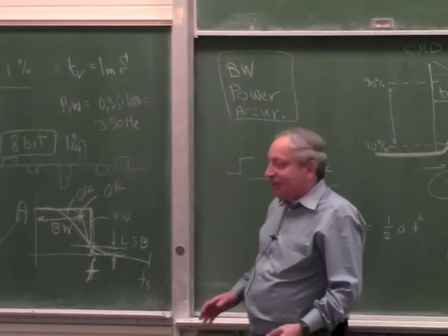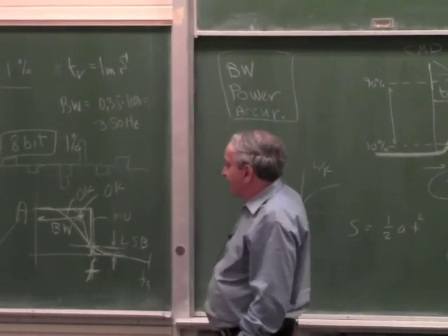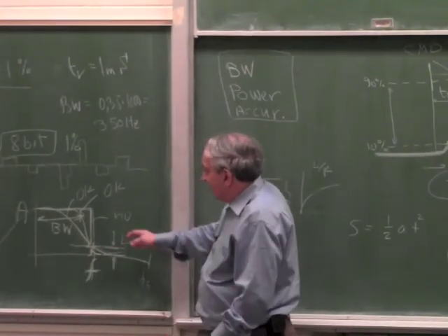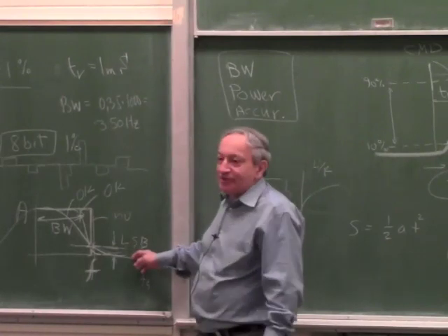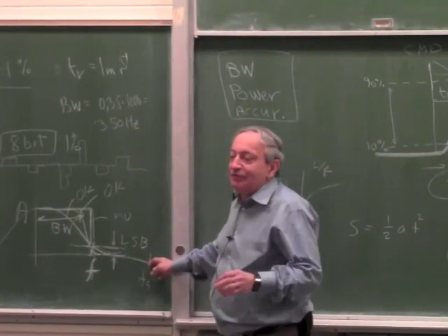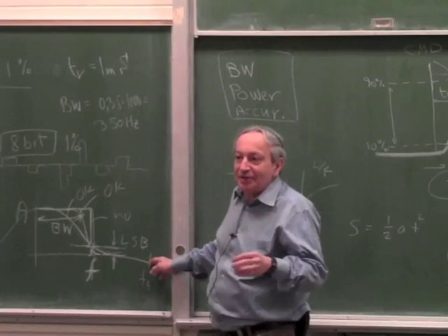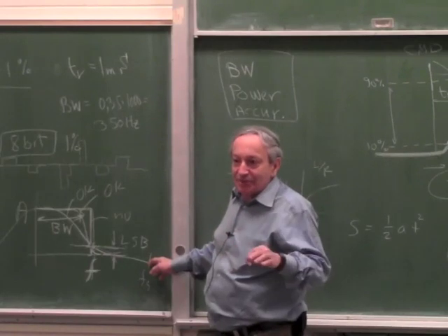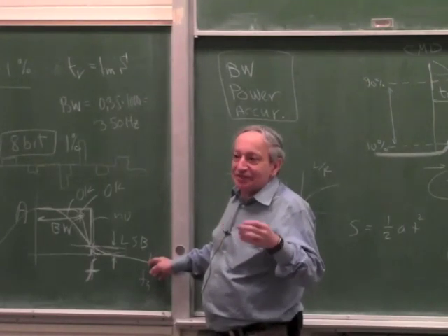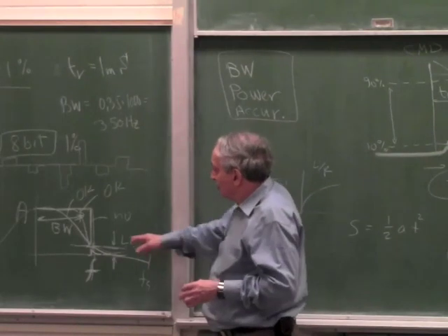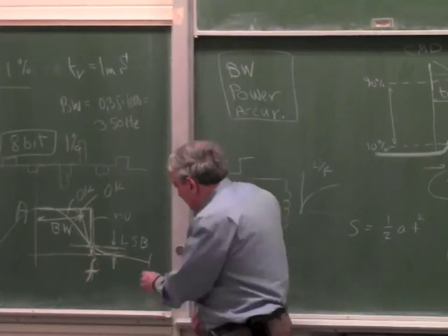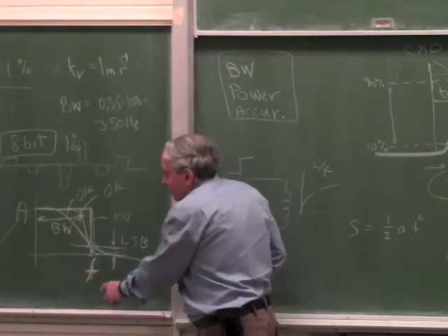But basically, the thing which determines the lower part of the graph is, you can't have like a 2/3 or 3/4 sampling frequency. You can have nothing. Because at the sampling frequency, if you have a sine wave of 1 kilohertz and you sample it at 1 kilohertz, you get just noise, just garbage. It's all aliased. So in order not to have aliasing, the signal should be less than half the sampling frequency. We went through this. So if you don't want to introduce even the one least significant bit of aliasing, then this actually should be half the sampling frequency. This is F and this is half F sampling.